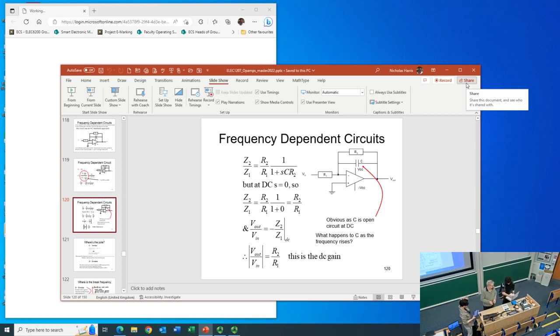The capacitors go away, right? At the signal frequencies, okay, not at DC. If you're doing a DC response, to calculate collector current, capacitors are open circuit. Okay. I might ask you again next time. Is that okay? Yeah.